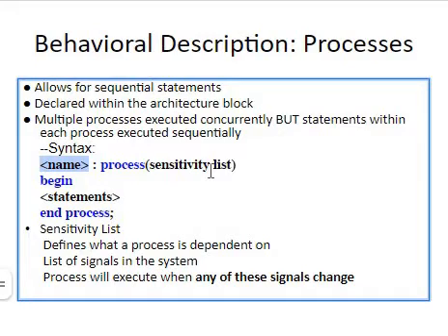Or else, a simple way is to use d only, data. So whenever the new data comes, the process will start. Then you have the begin of the process, and you write your statements, whatever you want to do. Say you want to assign a as 0, then this is 1 0, and so on, and end process.